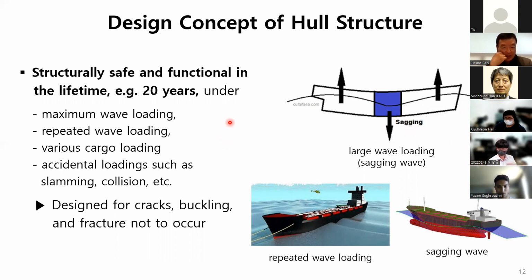Basically, hull is designed to be structurally safe and functional in the lifetime of about 20 years, sometimes 25 years, under maximum wave loading, repeated small and medium-sized wave loading, various kinds of cargo loading, many accidental loading, such as slamming impact, collision, grounding, etc. I'm going to talk about those loadings in more details later.